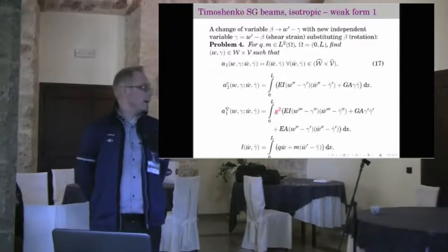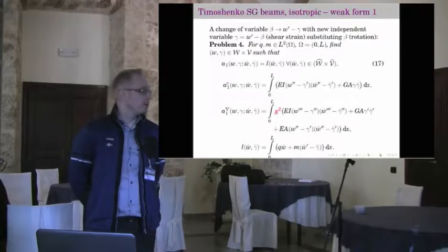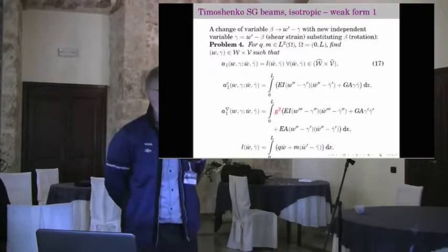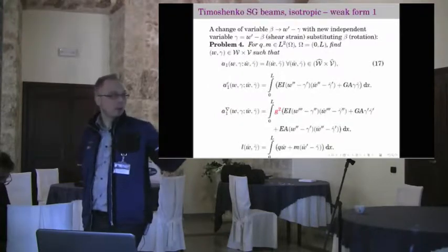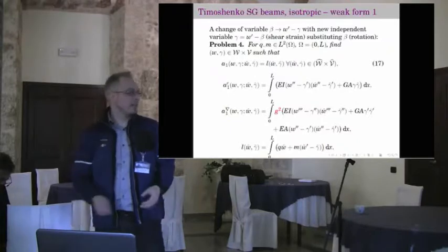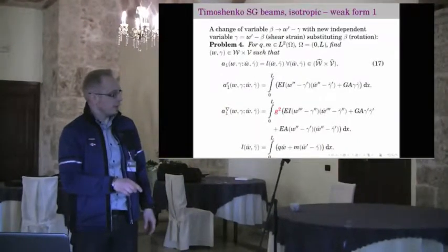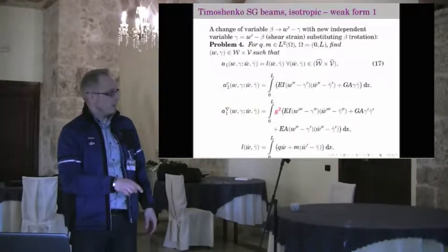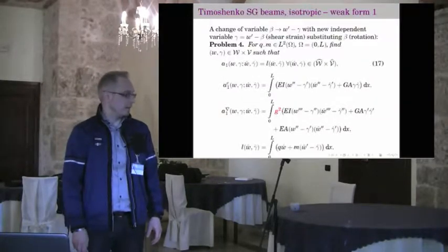And that's why we introduce another weak form where we actually take shear strain as an additional variable. This is quite a well-known and used technique from recent years. But still one can see that what we get, because here now we don't have any locking term here, but we still have one locking term here. So we have EA plus these minus signs here.